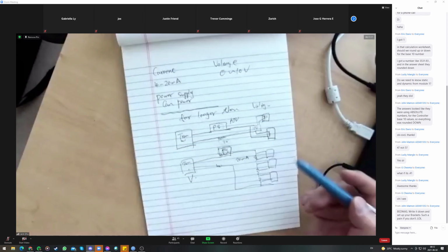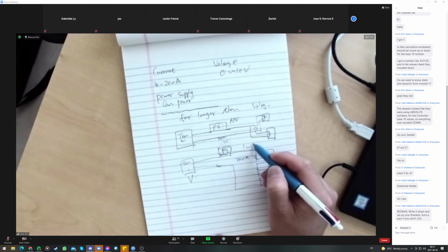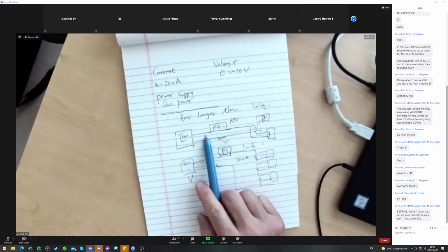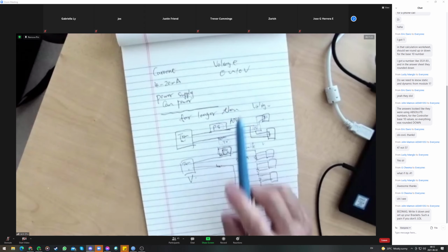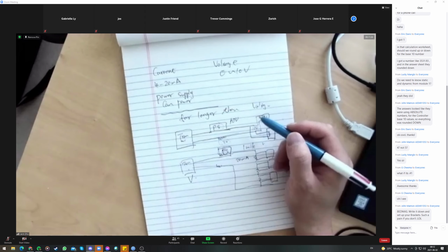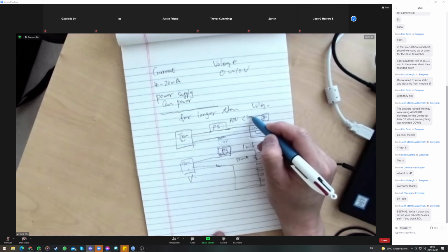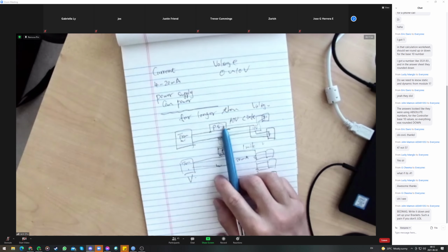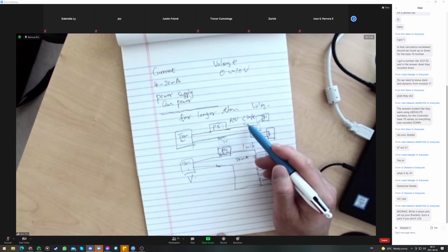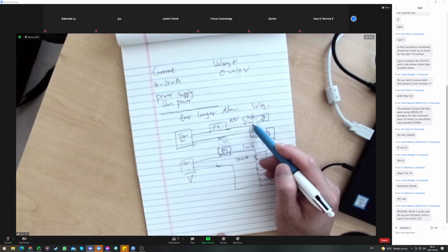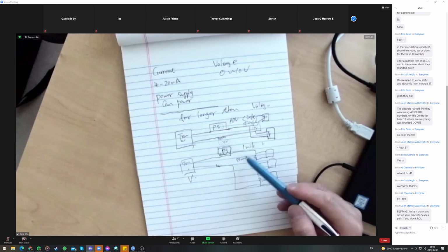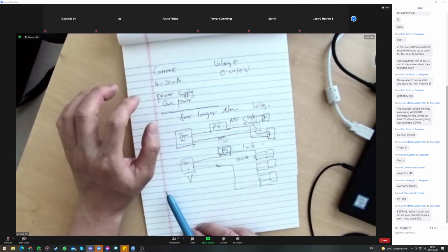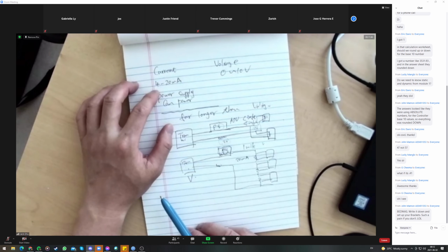Like we said, you can go 1 mile, like the calculation we did, half a mile. But for a voltage signal, it is usually less than 300 feet. You will not go more than that. The common one for voltage source is usually around 100 feet. So when they compare this to that, they said, okay, the advantage is this one can go far away.